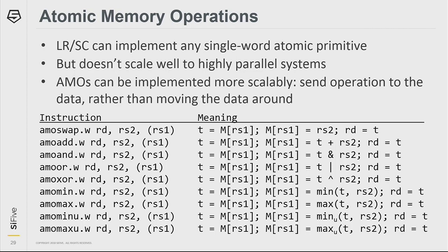There's also a more subtle reason why we provide them. They're useful for I/O. So if you want to do something like, say, toggle a GPIO pin, you can use an AMO XOR instruction on that GPIO register. Some other platforms have gone to lengths to provide that same facility without using AMOs. It's just kind of ugly. This works pretty well.